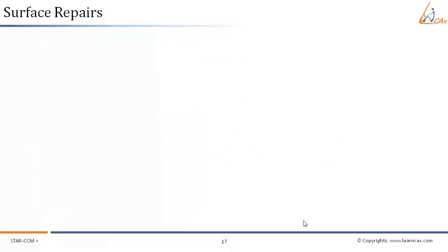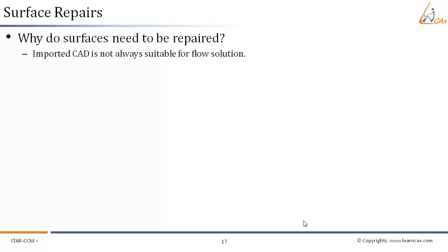Next we see that we need to repair surfaces. First, let us try to see why we need to repair imported surfaces. Imported surfaces are not always suitable for flow solution. There are too many details in the CAD model.